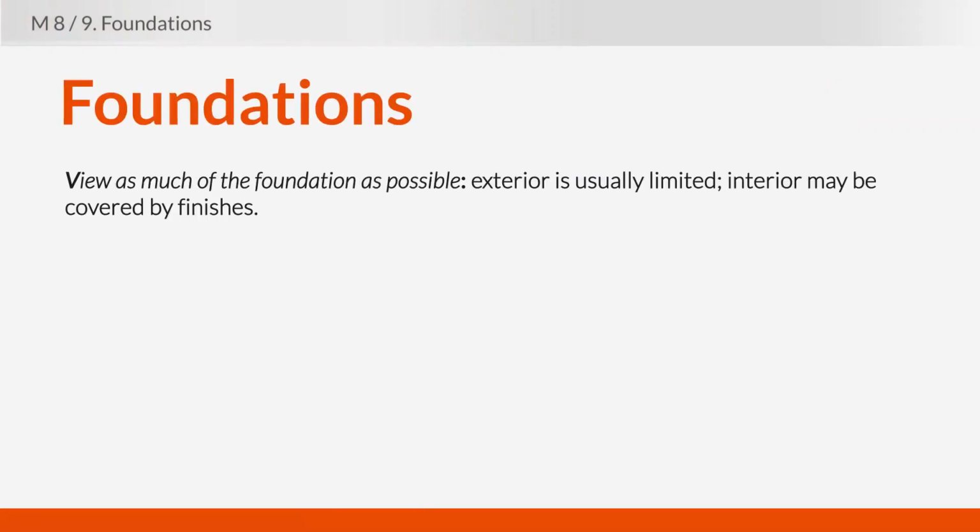We have made it down to the foundation. You should view as much of the foundation as possible. You usually can't see too much around the exterior, but still take a look at every area that is exposed on the exterior. And when you get to the interior, hopefully not too much of it is covered by finishes.